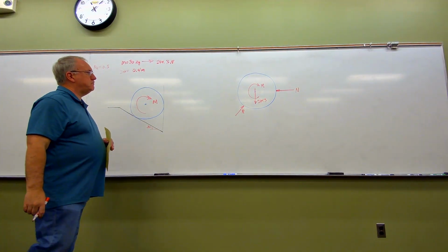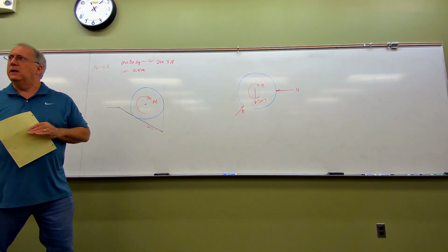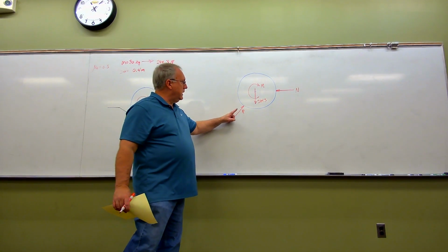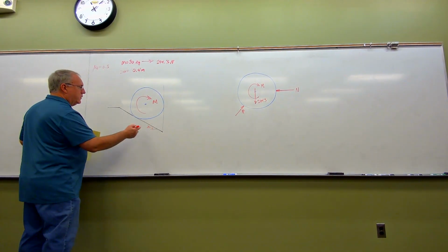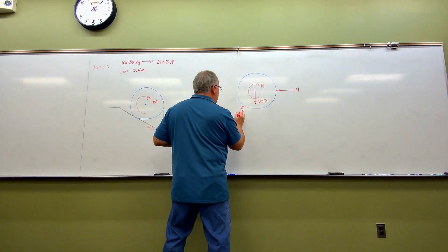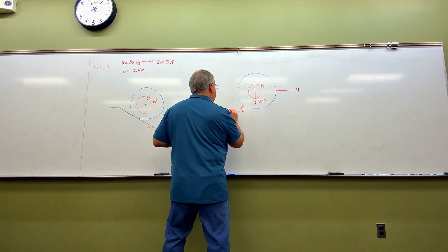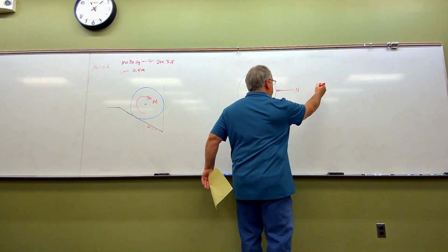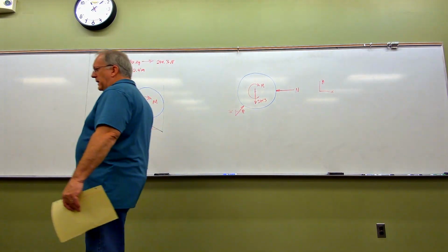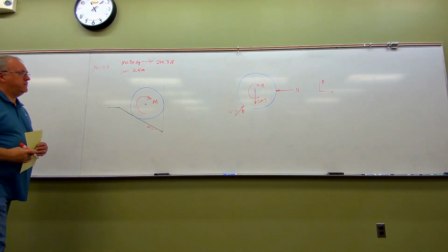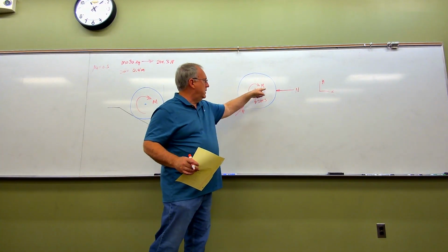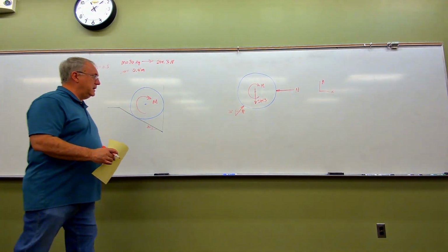It is worth noting too, folks, and that's just a little thing I want you to see, geometrically speaking, if this is a 30-degree angle right here, then that means that this angle here must also be 30 degrees. So I got 30 degrees right there. I am, by the way, going to use the standard XY axis system this time around. So let's keep that in mind. It's worth noting that the line of action of the normal forces, anything circular like this, has to pass through the center. It's worth remembering that. That's going to be useful for us in a minute.